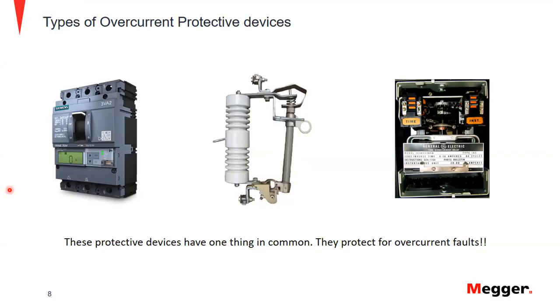And then the third thing we have is the electromechanical relay. What this does is it senses fault conditions by using CTs, or current transformers, that are either coming from a breaker transformer or even some external CTs that are in the yard. So when the predefined setting of the overcurrent relay is exceeded by the tap value, the disc will move and close a set of contacts, which attach to the circuit breaker trip circuit. And therefore it'll open the associated breaker that's tied to the trip contacts of the electromechanical relay.